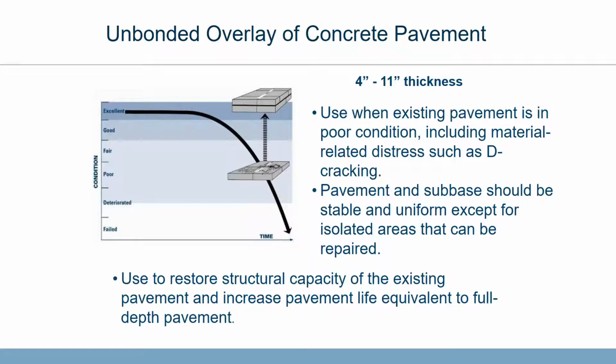The DOT was trying that as an option to see if we could do concrete overlays. And like many DOTs, we did do that. The bonded was not probably the best selection in that case, although it did last for 11 years. The DOT thought it might last for 5. And when they tore it out, the only thing that was left of that pavement structurally was the overlay itself.